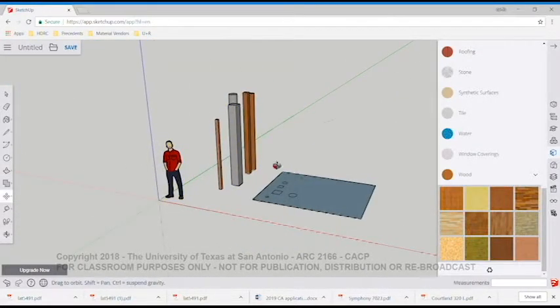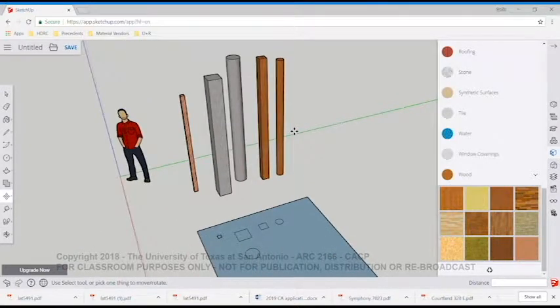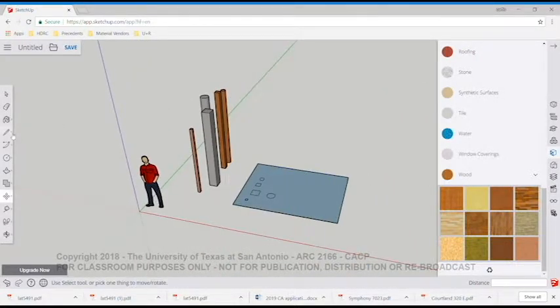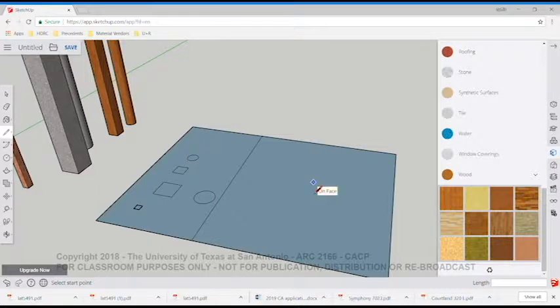So there's kind of a set of columns. In your project, you probably are going to choose one column and just go with that column. The second profile, and I'm going to kind of make a line on my sheet of paper here to explore those, are beams. And beams are always, maybe not always, but most of the time, they're going to be deeper than they are wide because of the way that forces act on them. We need a greater depth in a beam than we do a width in a beam.